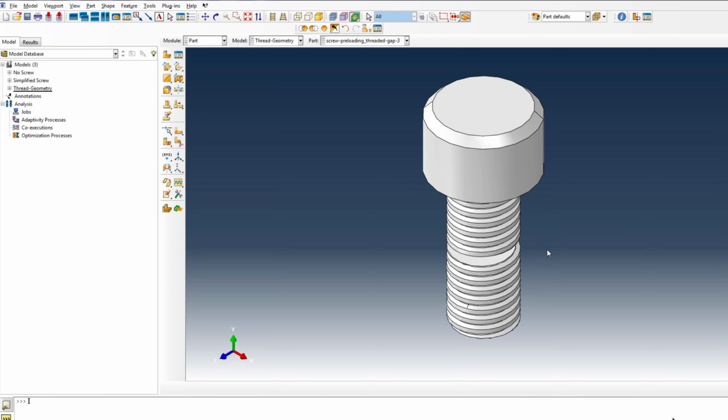and this is reasonable because when we tighten a screw, it's, let's say, a quasi-static event and not a transient or a fast event where we want to capture the behavior of the structure in short periods of time, something that the Explicit solver is designed to handle.